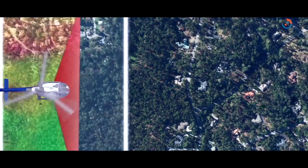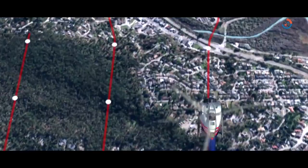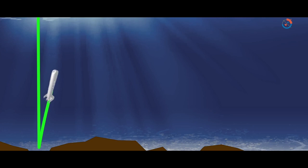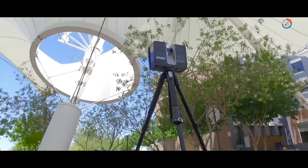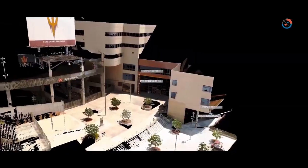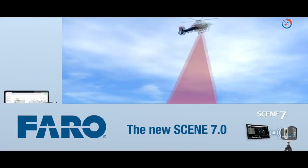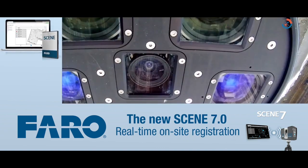There are three types of Lidar. Topographic Lidar. It maps the land typically using near-infrared light. Bathymetric Lidar. It uses water-penetrating green light to measure sea floor and riverbed elevations. Terrestrial Lidar for mapping buildings, natural features and trees at ground level. It is also very useful for 3D models of heritage sites.